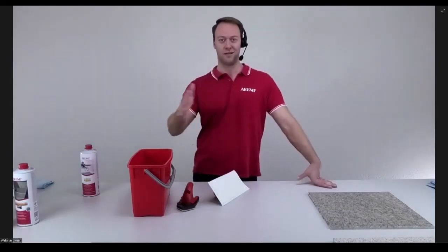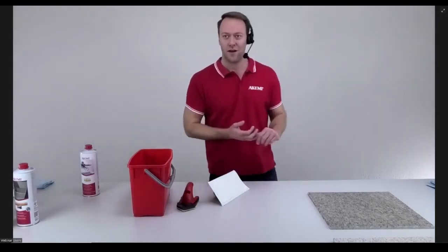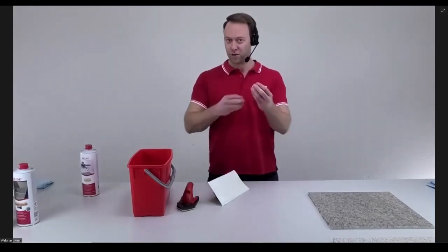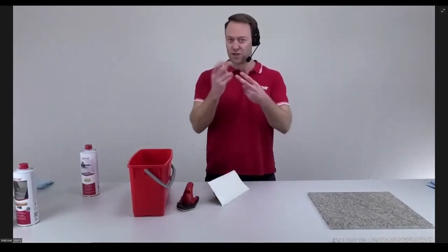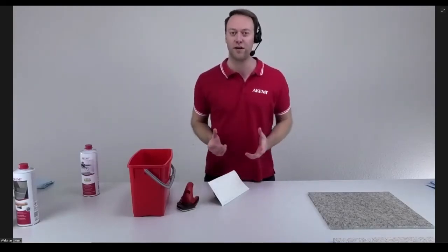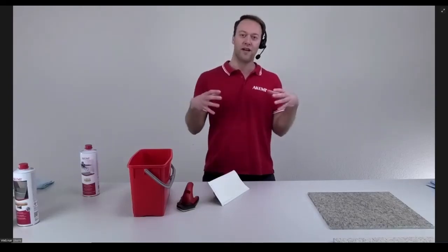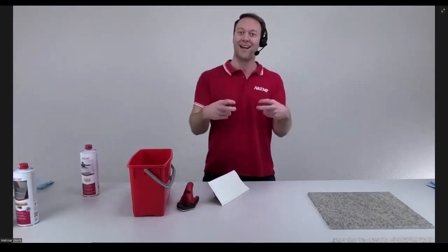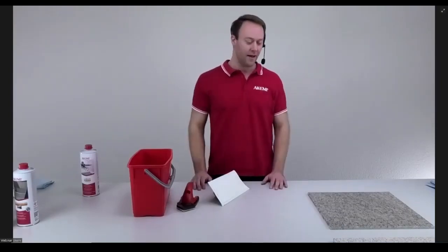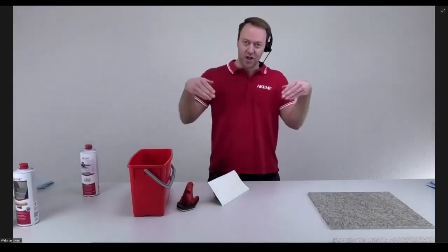That's affected by the weathering. So the stones erode. Some small stone particles disappear from the surface. So any impregnation or sealer which attaches to these stone particles also gets removed, of course. Obviously, the impregnation penetrates deep inside the stone, so there will still be some protection, but not the same protection like on the first day.